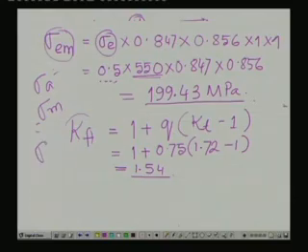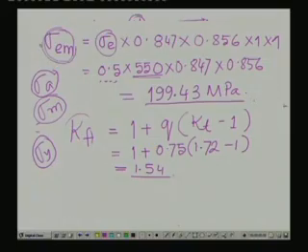You require the sigma yield point, isn't it? So, we require sigma yield point, sigma A, sigma M, the endurance limit for the machine member to be designed, and the fatigue stress concentration factor Kf.